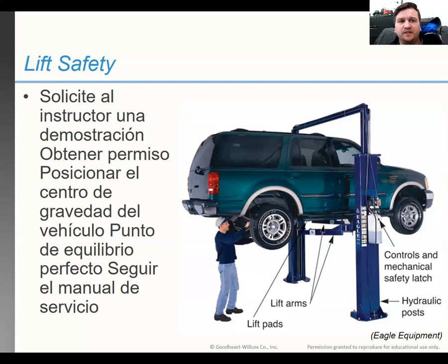All right, so lift safety. Right here is a good picture of a lift. You can see a gentleman working on the rear suspension or something like that down below. This is a 2-post lift. So anytime we use a lift, you're going to want to ask your instructor for a demonstration. That's me. Get permission to use it. Position the vehicle center of gravity where the center of the lift is. So here on this 2-post lift, you'll want the center of gravity right next to where the posts are. Right here, you can see the post and center of gravity.